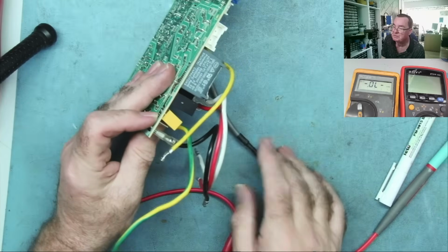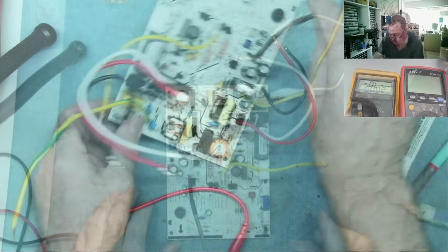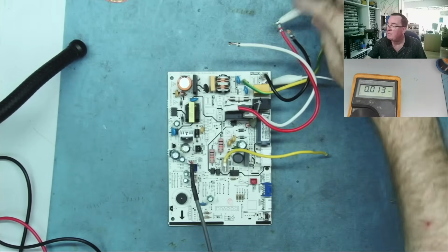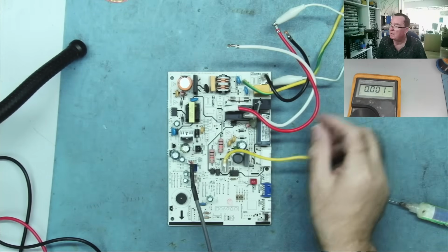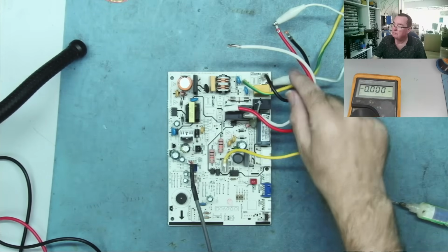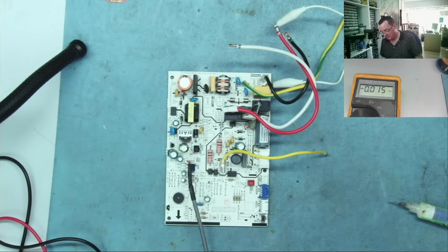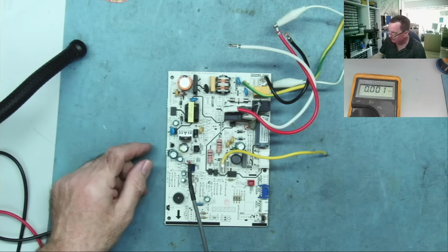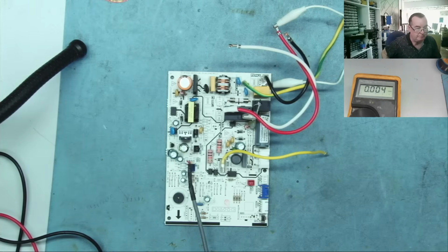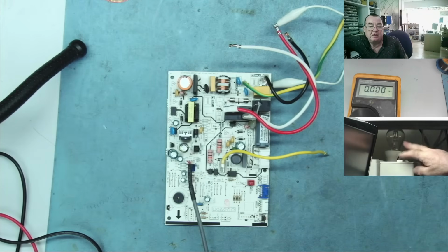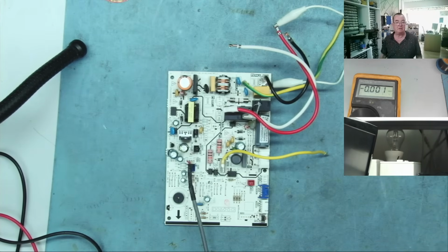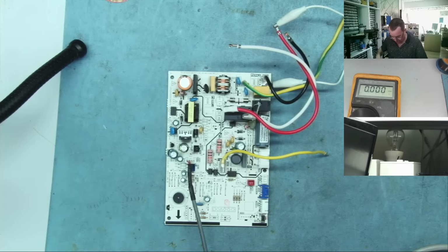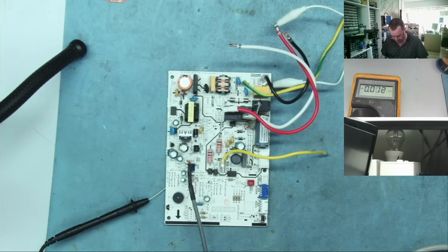Right, let's power this up and see if the power supply comes on. Okay, so I have my mains applied between the red wire and the spade terminal. I've put the current limiting light bulb in because it's always a good idea when you're doing things like this. And we can see that over there, so that's set to limit. I'm going to switch it on. Now, how will I know if the power supply is working? Well, if it doesn't blow up or something, it shouldn't do because of the current limiter.